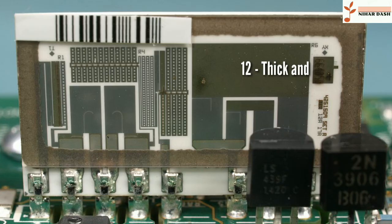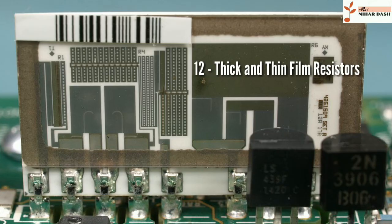Thick and thin film. Laser trim precision thin film resistor network from Fluke, used in a Keithley DMM7510 multimeter. Ceramic backed with glass hermetic seal cover. Thick film resistors became popular during the 1970s, and most SMD, surface mount device, resistors today are of this type. The resistive element of thick films is 1,000 times thicker than thin film, but the principal difference is how the film is applied to the cylinder, axial resistors, or the surface, SMD resistors.